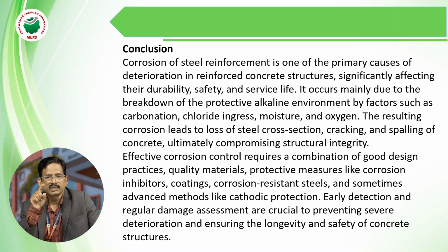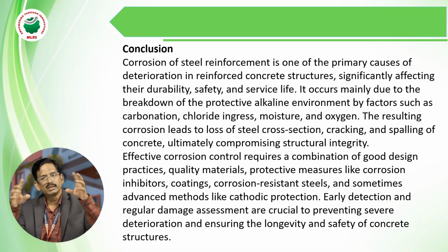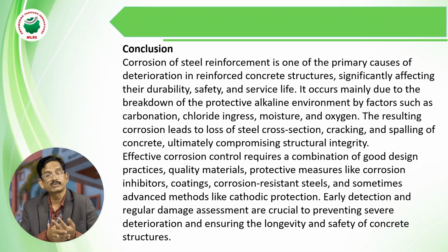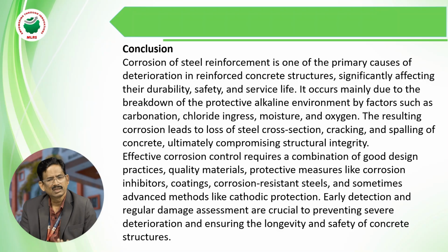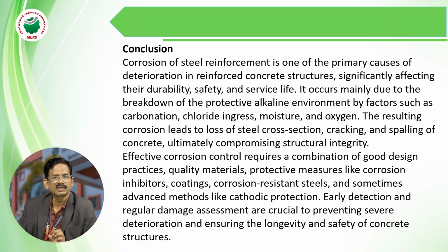So that's why one of the reasons is the cross-sectional area will be reduced, and then the spalling of the concrete, and the third one is structural integrity will be disturbed. Structural integrity means the unity of the structure. Why? Because in the building different structural elements are there: slabs, beams, columns, staircases, shear walls, footings, floorings, water tanks. So many structural elements are to be there within the building itself.